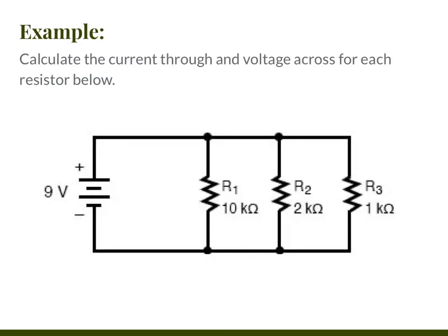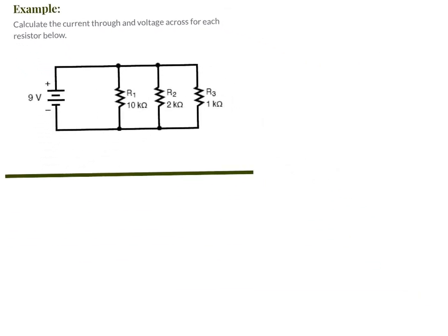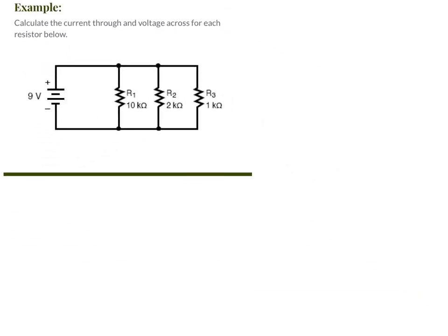Here we've got that same thing, 3 resistors connected in parallel. To find the equivalent resistance or the total resistance, we're going to have to do 1 over each of these things. Yay for fractions. We do 1 over the total resistance in parallel equals the sum over i of 1 over Ri.